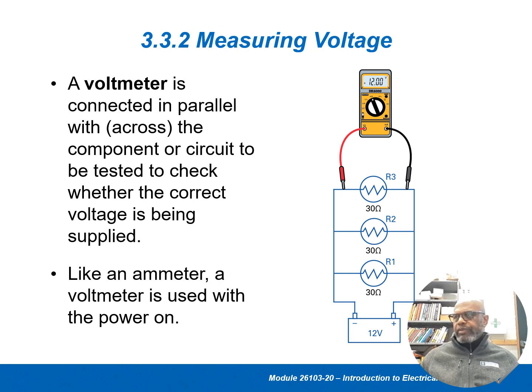Now, reading voltage is very simple. We just put our meter in parallel with the load. So in other words, it looked very similar to this when we were reading the amperage, but there's no wires disconnected. You just touch where there's a terminal someplace, on both sides of a load, to be able to determine. So again, if I put my meter on this and here on the power supply, I will read the same thing here and there, or here and there. So on both sides of the load, I will read voltage.